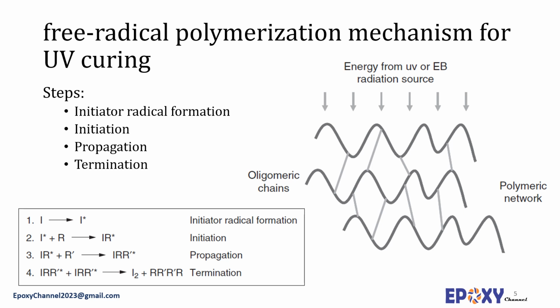Acrylic-based resins for UV curing are polymers or oligomers that contain unsaturated acrylic groups, either acrylic acid or methacrylic acid. Acrylic acid or its esters induce more reactivity to the resin and therefore are preferred over methacrylic acid or esters in UV curing systems. The following acrylate resins are technically in use: epoxy acrylate, polyester acrylate, polyether acrylate, polyurethane acrylates, unsaturated acrylic resins, and silicone acrylates.